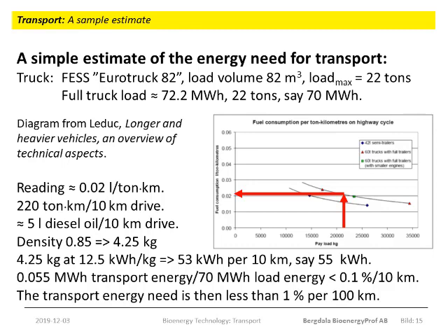And then 22 ton kilometers per kilometer, since the load was 22 tons. So 220 ton kilometers per 10 kilometers driving. That gives 4.84 liters of diesel oil per 10 kilometers. Make that 5 liters. Diesel density 0.85 kilos per liter yields 4.25 kilos of diesel oil. And then we have 10.5 kilowatt hours of energy per kilo of diesel oil.